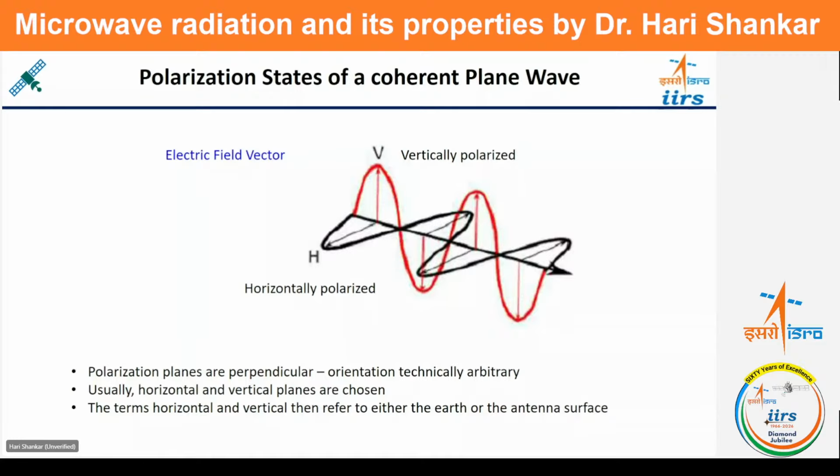is basically moving in the form of a sphere. So you can say the trace of that resultant vector is like an ellipse. In that way, that is the elliptically polarized signal. If both horizontal and vertical are there, then they form the elliptical polarization. If the amplitude of both the waves is the same everywhere, then the ellipse can be converted into a circle. In that case, that is the circularly polarized wave.